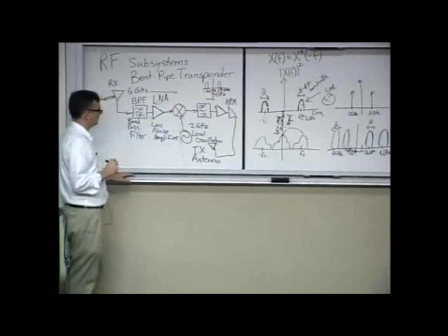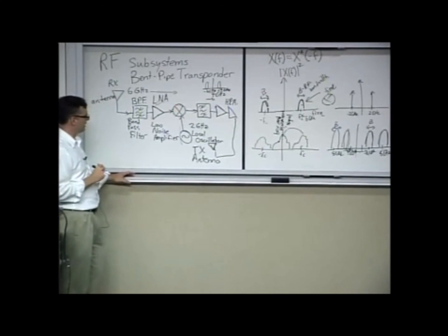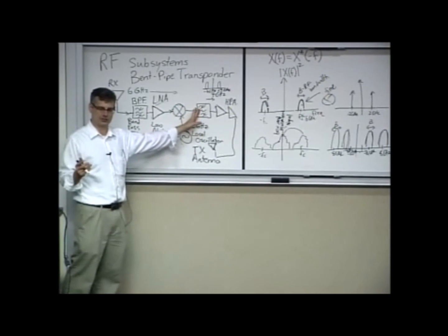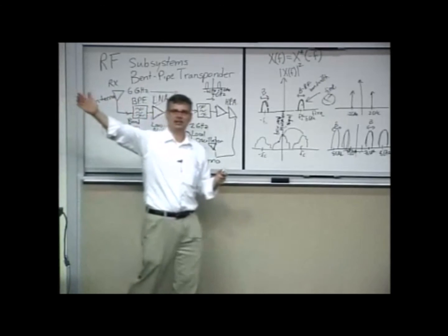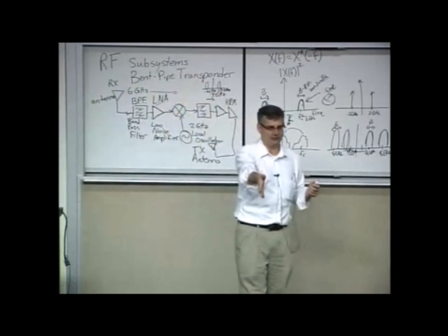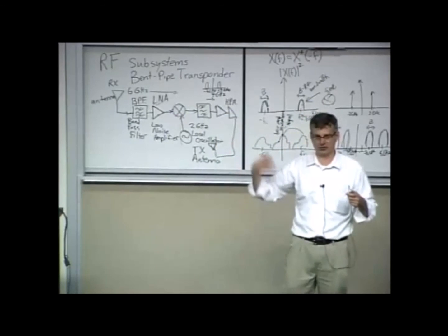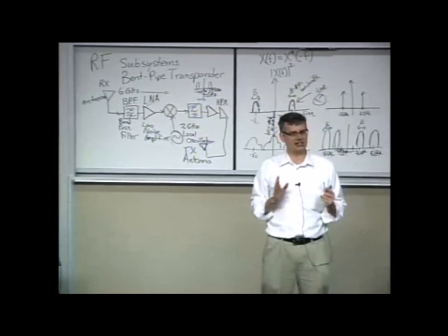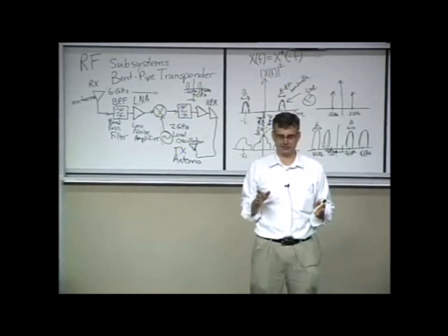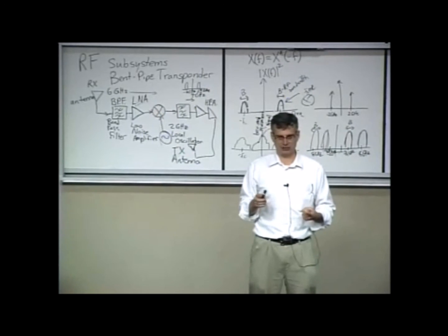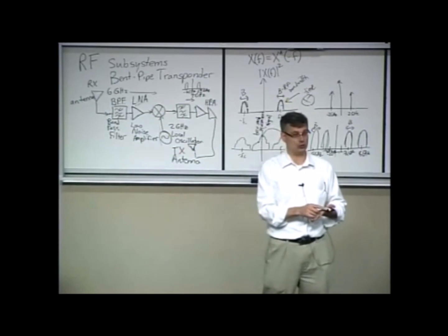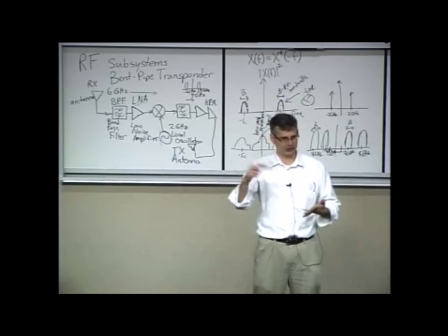satellite would do. You can actually do variations of this where you have maybe multiple stages in your transponder, even an analog transponder, where you mix a high-frequency signal down to what's called an intermediate frequency. This would be down at maybe the hundreds of megahertz or 1 gigahertz or something like that. And that's a nice frequency to operate at because it's much easier and cheaper to make good amplifiers with low noise figures, high gain, high linearity, high Q, or you can get the same bandwidth with a lower Q filter.